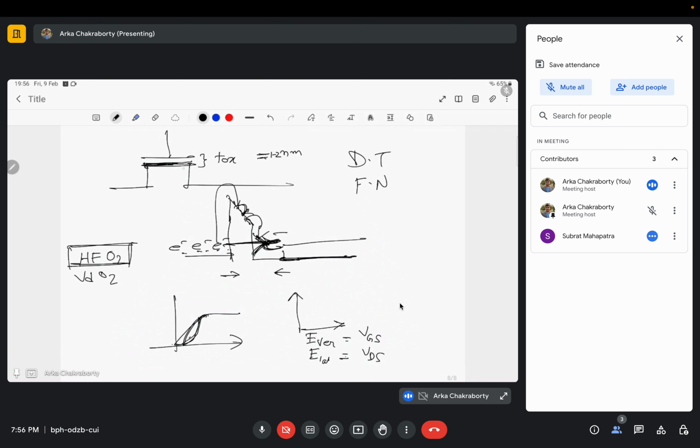Initially we were using silicon oxide, right? Now we use a small pad of silicon dioxide, and above it we deposit hafnium dioxide. So even with a small Tox value, we are able to reduce the GIDL effect. And this quantum tunneling leakage is used in one application.